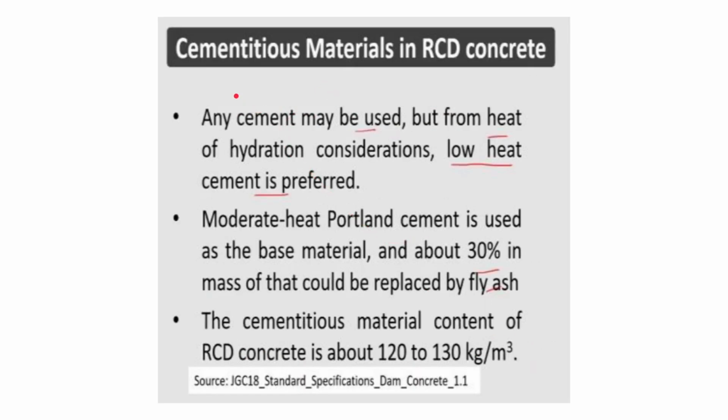So what are the types of cementitious material used in RCD? RCD means roller compacted dam concrete. Any cement may be used, but from heat of hydration considerations, low heat cement is preferred, because it is a mass concrete.